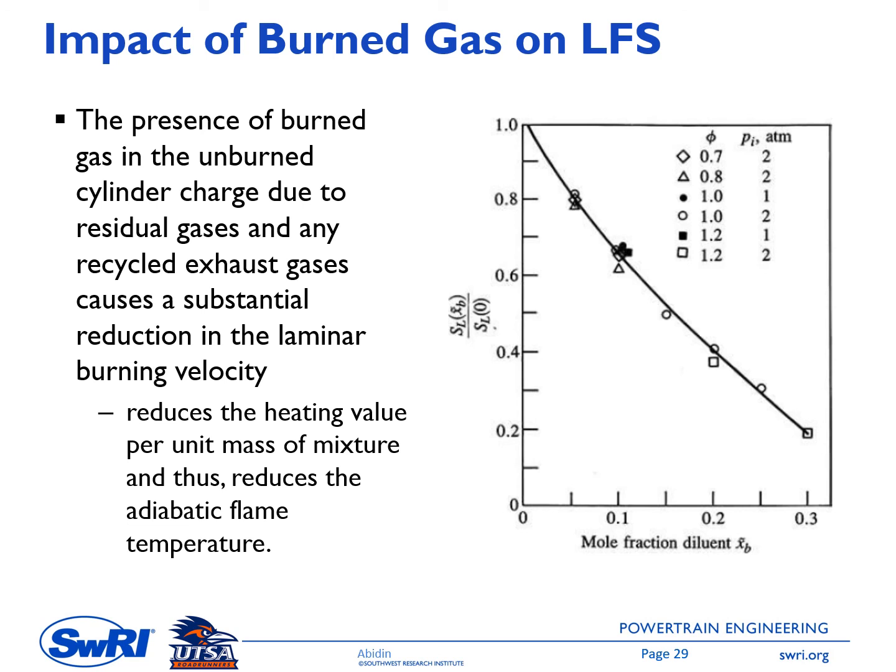Next one is, how does the burn gas influence the laminar flame speed? We put a special topic on burn gas because we use EGR. Right now EGR is the prominent option for reducing emissions, so we need to know how EGR influences the laminar flame speed. When we talk about EGR, we classify it as burn gas. We also have a different burn gas inside the engine, which is the residual, the burn gas from the previous cycle.